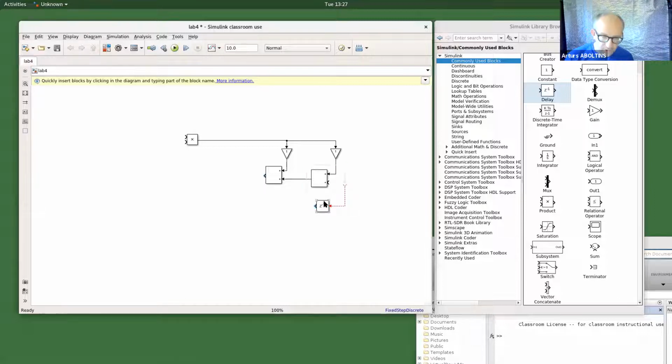Okay, I did it. I do not need to flip it, sorry. It was my mistake. It doesn't need to be flipped because it goes like this. This is a digital filter, a recursive digital filter with coefficient A1 equal to 1. This is the so-called ideal integrator.